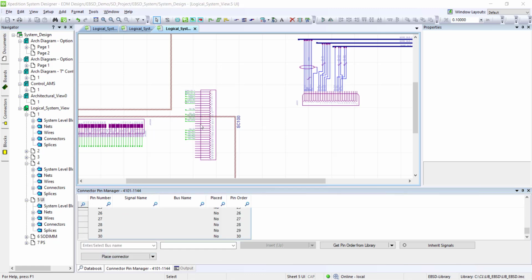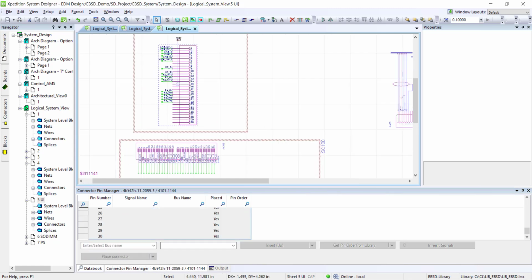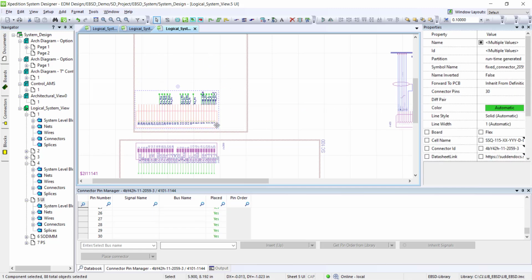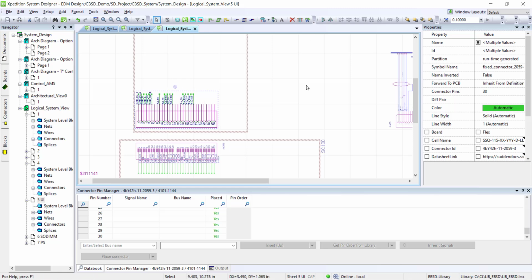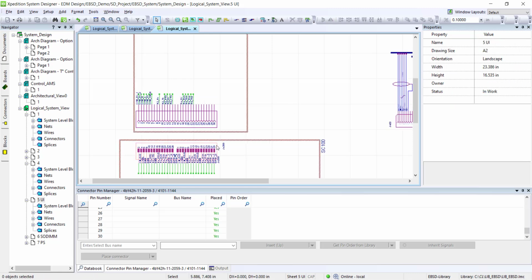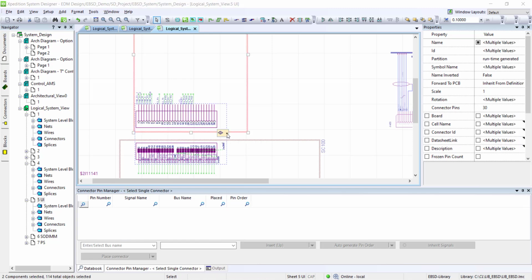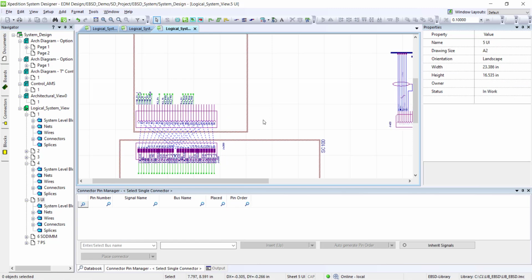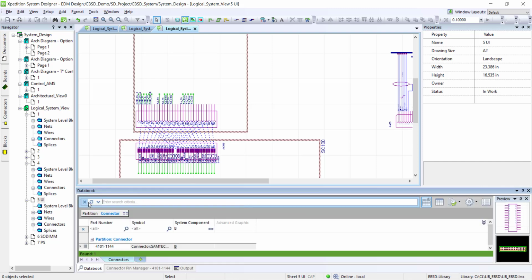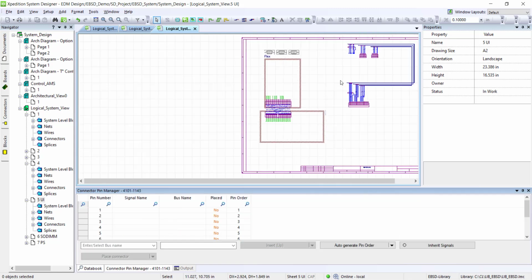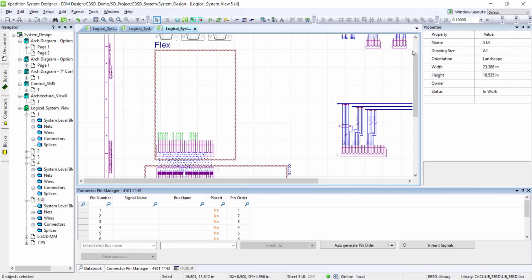After the desired connector is in the schematic, it still needs to be logically mated to the SC100 board connector, similar to how the cable connector was previously unmated. The remaining 3 connectors will be placed using a databook search. The signals for these 3 board connectors will be copied from the signals on the existing cable connectors the same way we copied the signals for the 30 pin.